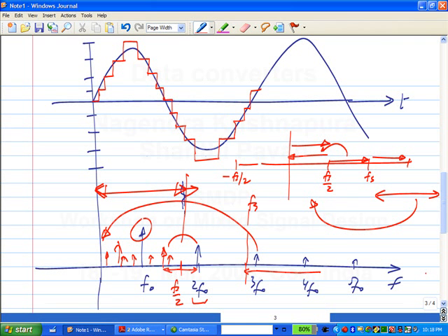This is okay? So that's what I was trying to get at. It is true that it will become noise, but how does it become noise? Why is there noise? This is what happens. You have harmonic distortion which gets aliased, and you have a large number of tones, an infinite number of tones. So they will fill up all the gaps between 0 and Fs by 2 typically. So that will look like noise, and that's what we call quantization noise.